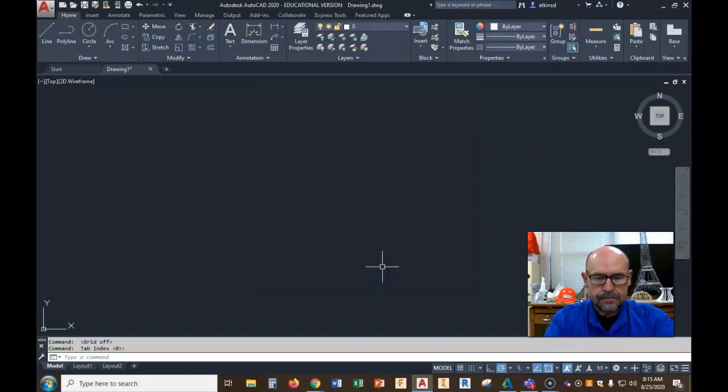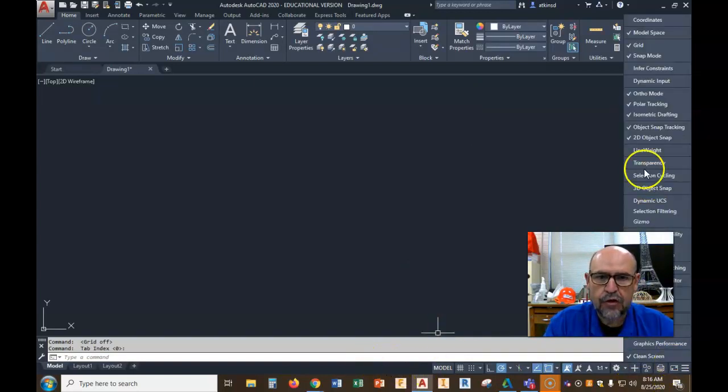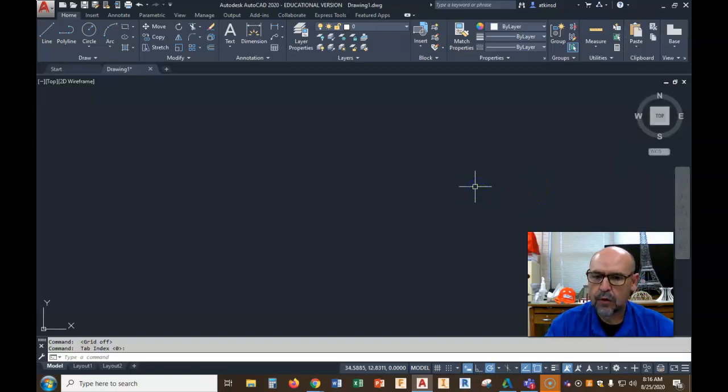I've got that set. The other thing I'm going to do, I'm going to cut my coordinates on down here so I can see them. I'm going to hit my customization window, and coordinates is the very top one. I'm going to click it on. I'm also going to click on dynamic input. That way the things up on the screen beside the cursor, if that ever goes away, it's this button right here. It looks like a flash drive with a plus sign beside it. Okay, we've got our coordinates cut on now, and of course line weight is the other one that I won't cut on. Those are all really important. Once I click in the screen with my left mouse button, they all go away. Everything's back to where it needs to be. As you can see, as I move my cursor around the screen, the increments change at the bottom.